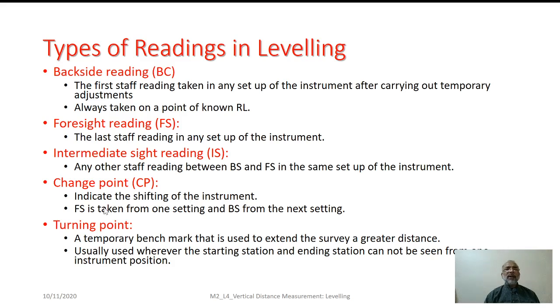In fact, change point and turning point are one and same, but this turning point terminology is usually used wherever the starting station and ending station cannot be seen from one instrument position, and we have taken certain temporary benchmark from where the work is continued. Practically, we can assume change point and turning point to be one and same, which is nothing but the point on which both backsight as well as the foresight is taken in order to continue the leveling operation.